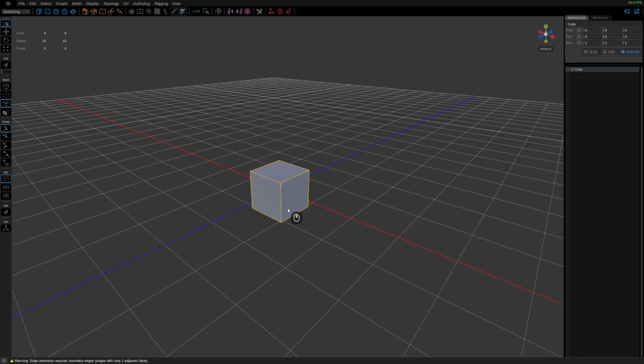So we select the edges and then press Y, which is the shortcut for bevel. We could also hold Ctrl and right click. When you right click normally, the radial menu shows the control modes, but if you hold Ctrl and hold the right mouse button, it gives you the poly modeling options. These are the same options shown here, so we can select bevel this way as well.